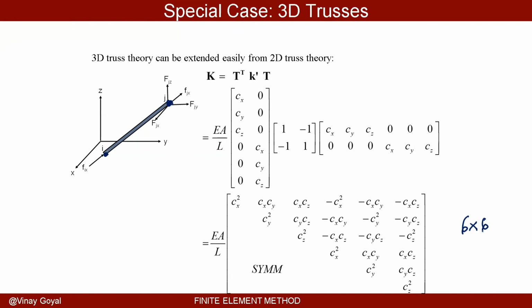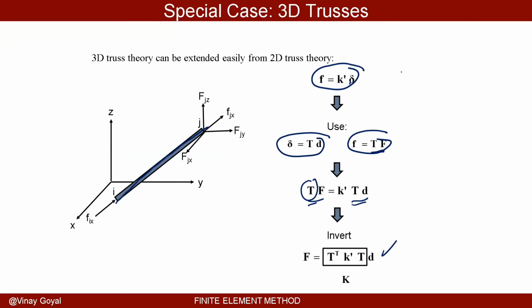We're able to succeed and put everything together in a way that makes sense. And so I do want to point out that 3D elements in Abaqus are going to be T3D2. 3D elements, 2 nodes. And again, all we've done is a little trick.